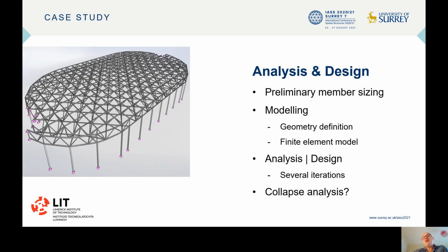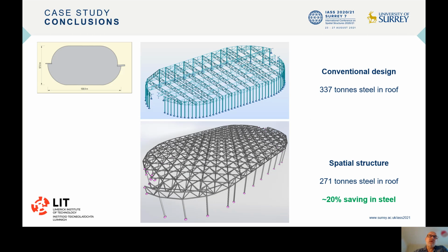The case study then goes through analysis and design of the double layer grid solution, including preliminary member sizing and several iterations of analysis and design to refine the design, with finite element modeling and analysis done using LARSA 4D software, and some of the results of that presented.